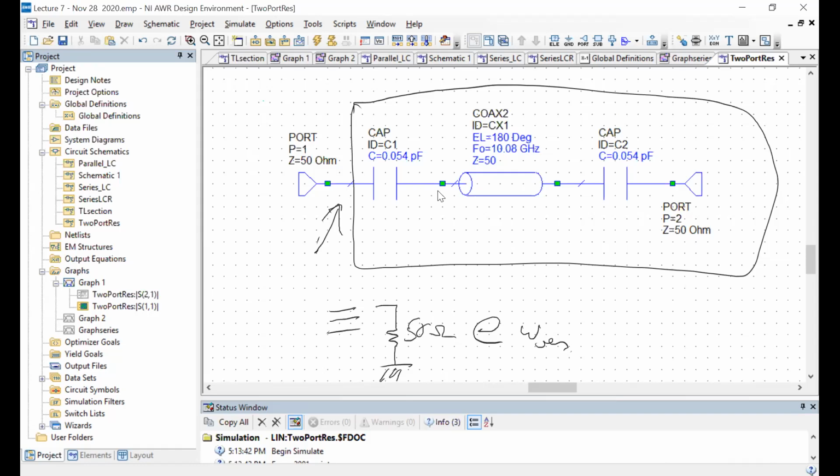Of course, now you know that here it's a transmitting system, but if you only had this information, then the only thing you can extract out of it is that it's perfectly matched to 50 ohms at that particular point. Okay, is that clear? This is the only information you have, and if you have a reflection coefficient of 0, it is only possible if the impedance is real and equal to the impedance of your port.